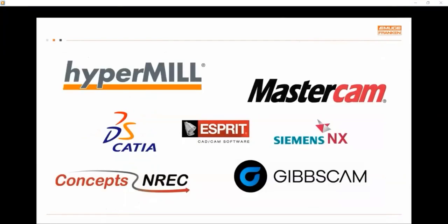And then we have our CAM softwares. One of the biggest hurdles to get over is, how do I program these tools, right? The CAM softwares that support these tools actually have to have support for the geometry and the tool paths and everything like that to actually utilize these tools. You can't just throw it in any CAM software and put just a raster back and forth, a zigzag tool path on it, because you're not just using a ball mill, you're using a segment of a circle, and there's a lot of calculation behind that.